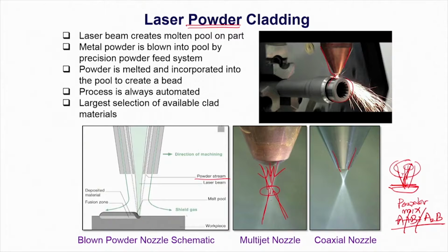The relative movement of the workpiece with respect to the laser, either the beam is moving or the workpiece or the stage is moving. Either way, we create a relative motion, and that will determine the interaction time, and this interaction time, apart from the power density, are the two process parameters, just like any other laser material processing.